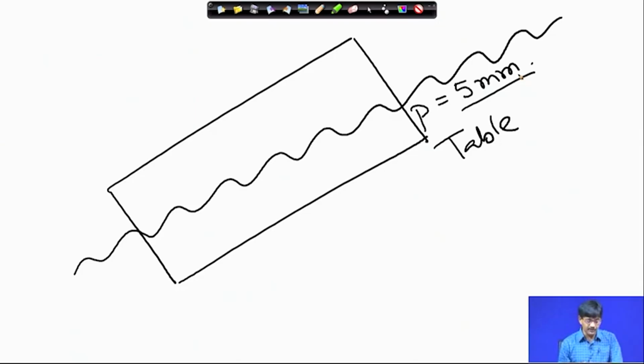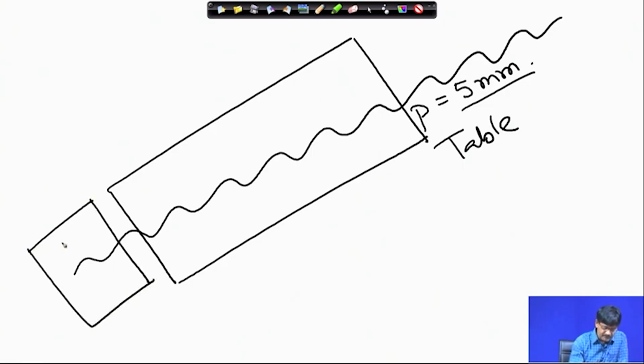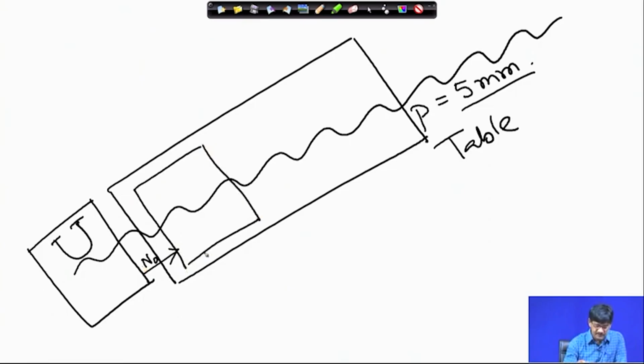And what did we do after that? We connected a gearbox here. So, let that gearbox ratio be U. If U is the gearbox ratio, it was ultimately giving its output, let us call it N0, to the indexing head, and in the indexing head it undergoes a change in rotation, and ultimately it is giving that rotation to the workpiece.